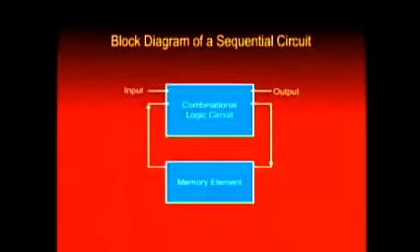Consider the timer of a microwave oven. You key in the time to cook your favorite dish. The microwave display unit displays the cooking time. The memory element of the microwave oven sequential circuit stores the cooking time. The cooking time is decremented by 1 after every second when a new input signal is received at the input of the combinational part of the sequential circuit. Ultimately, when the cooking time decrements to 0 and the memory element stores 0, the next input signal sounds an alarm and turns the microwave off. Similarly, a traffic signal controller operates in a similar manner. It switches between the green, amber, and red signal in a sequence on the basis of current and previous information.